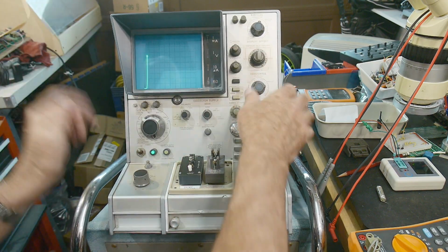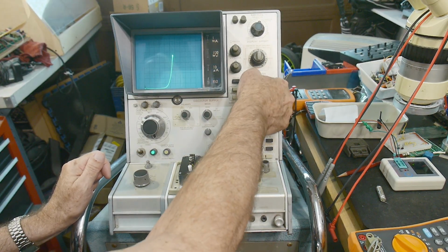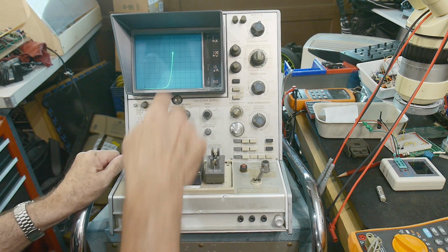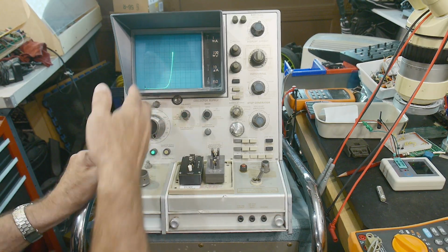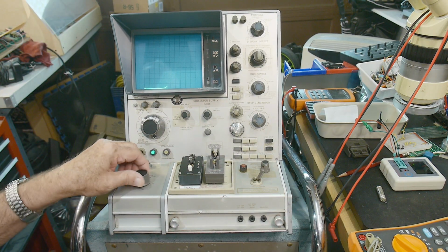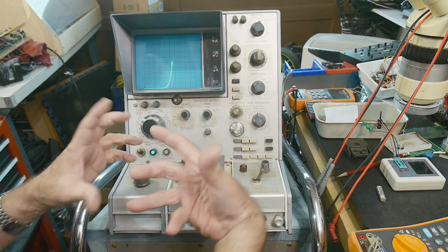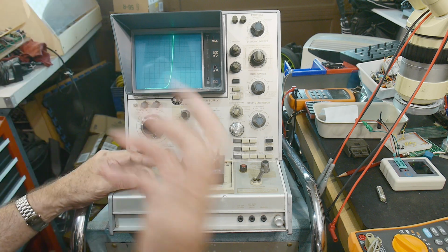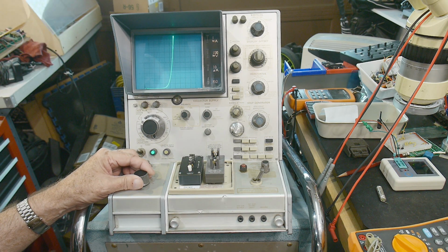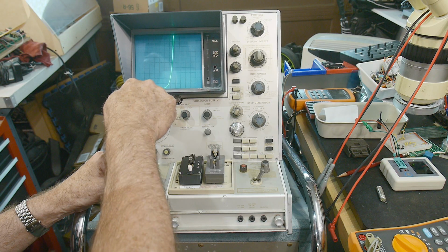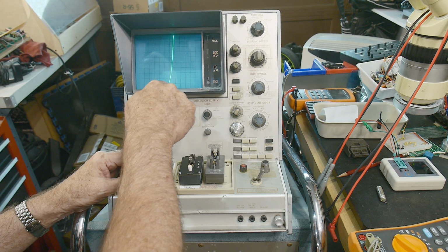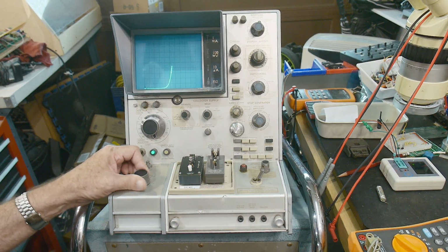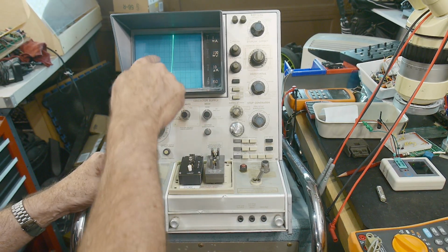Well, we can take a look at that better. We can change the horizontal scale of our machine, and now we see this curve. Well, that's a diode curve. So many milliamps is so much current, right? The higher the voltage, the more you turn on, the more you're able to pass through the diode. So this diode right here, 100 millivolts per division, so it's 1, 2, 3, 4, 5, almost 0.6 volts to get to 10 milliamps. 10 milliamps is at the top because we're at 1 milliamp per division.